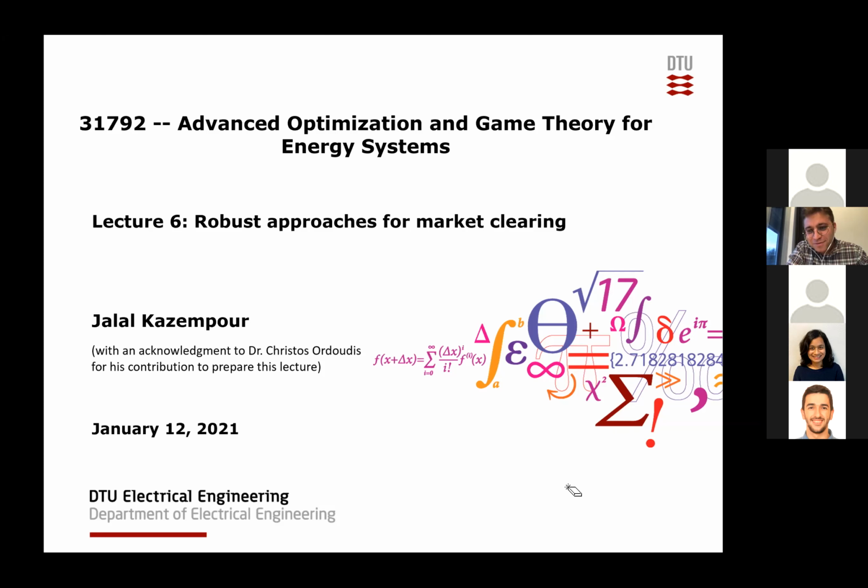Assuming that we have 2 wind farms, and these green dots are historical data, and the 2 wind farms are correlated. It means that the worst case for the 2 wind farms will not happen at the same time, right? We can learn it from the historical data. And here, as you see, the uncertainty set ends up as a polyhedron,